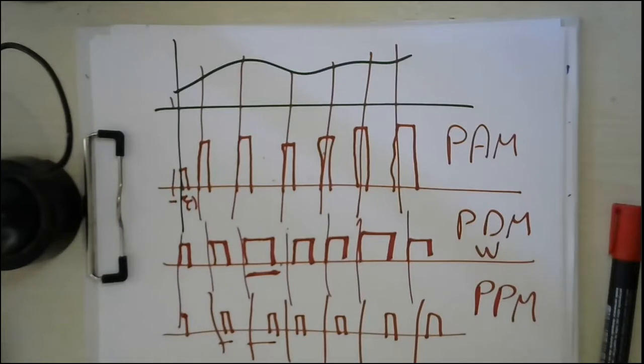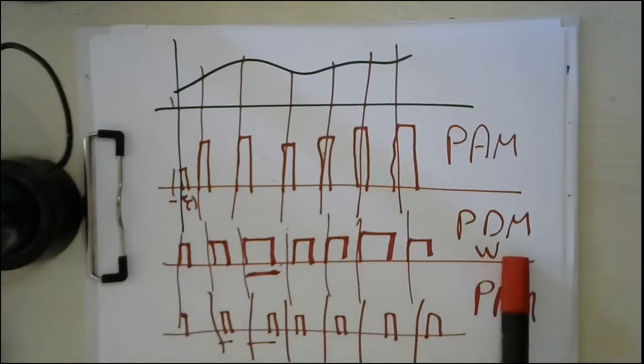Or, I would say it in another manner, your carrier becomes some sort of impulses, not a sinusoidal signal. Basically, this is one of my previous questions in a previous lecture, a bonus question: why are we using sinusoidal signals as a carrier? Simply because sinusoids give the minimum bandwidth ever.